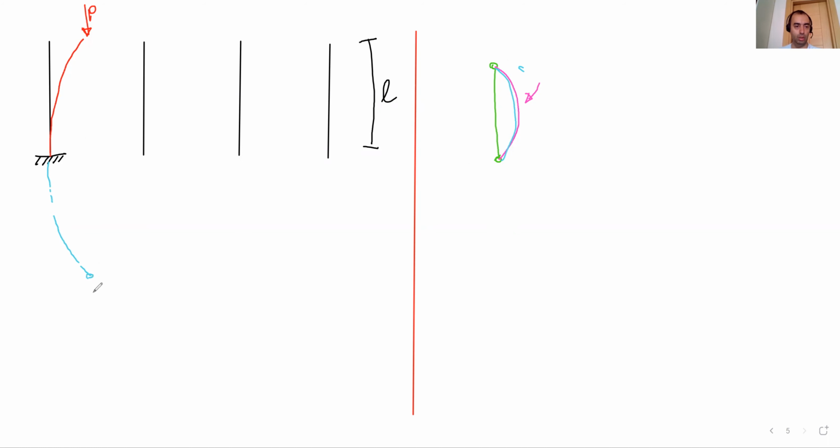So what I get here, I guess this is L, this part. To get the fully arched shape, I need one more L. So LK for this vertical cantilever is 2 times L. The buckling length for the vertical cantilever is double L, as you can see.